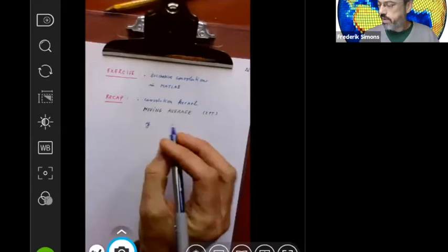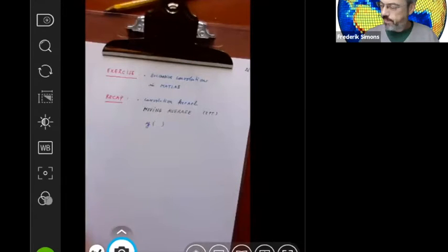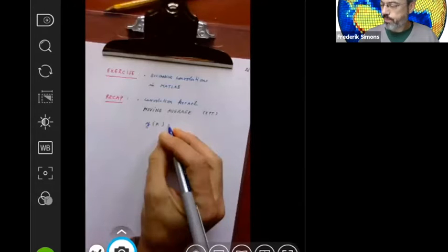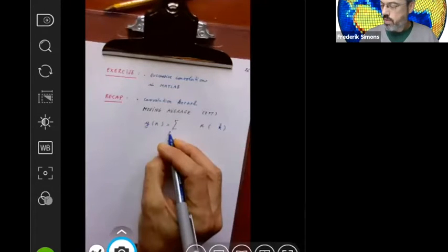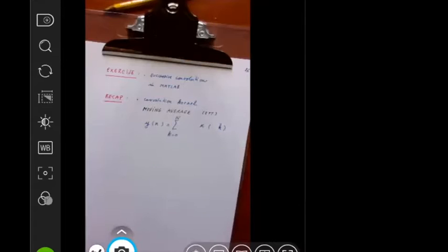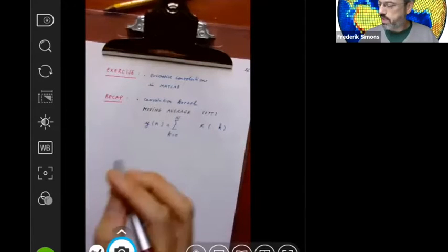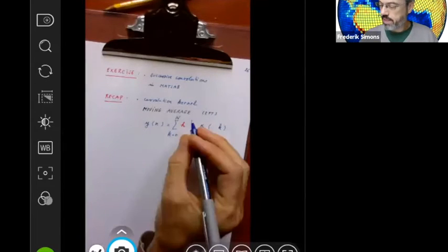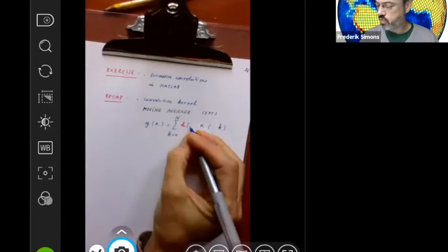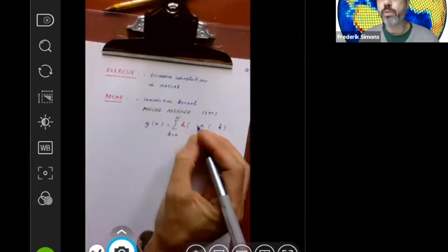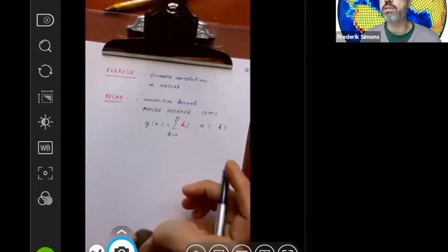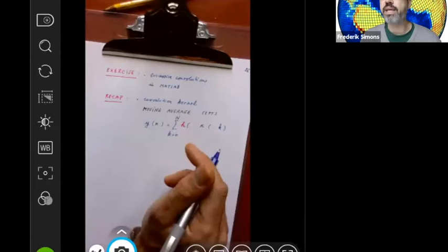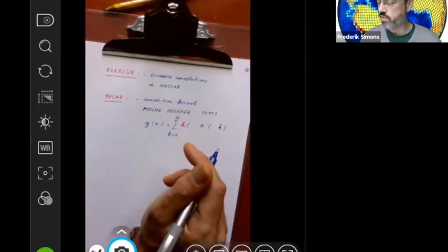I'm going to rewrite y of n as a convolution of some input sequence with a certain kernel, and I want y to be the moving average of the signal x, where the average pertains to 2 points at the same time. To smooth something, like if you look at the weather or your stock exchange and you say, give me the moving average over a day, 5 days, a year, lifetime of funds.